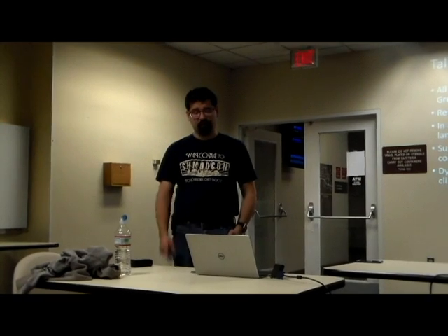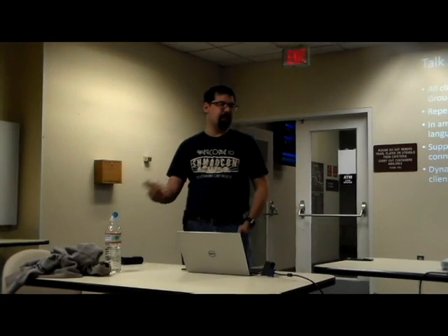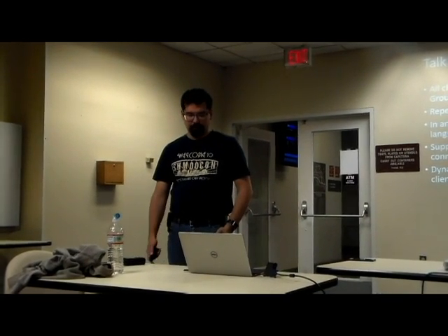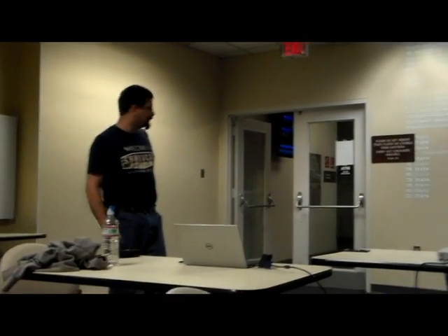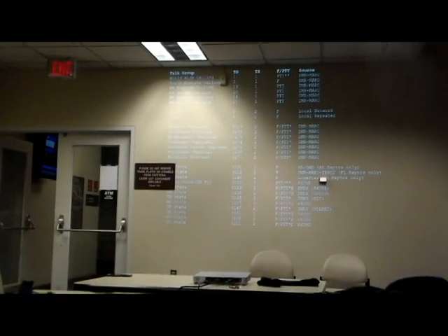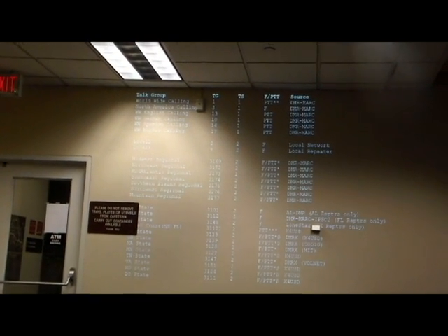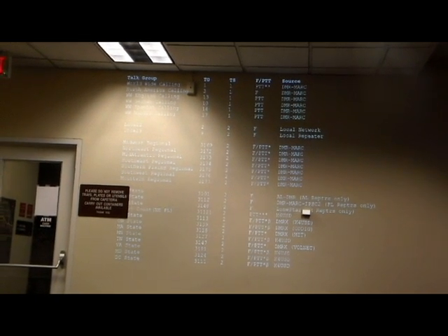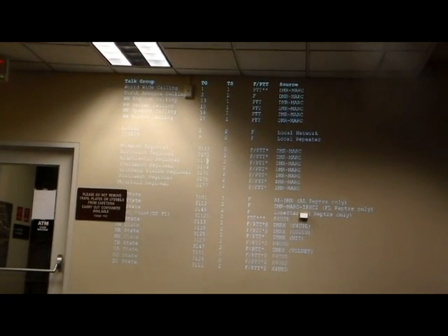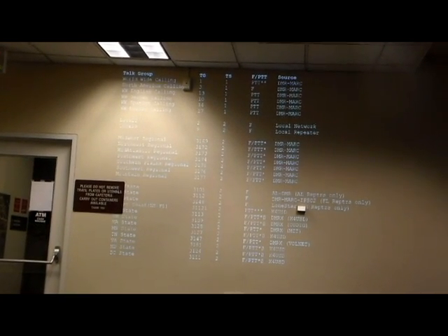Generally, when you do activate one of those dynamic groups, there's some kind of timeout involved with it, maybe 5 minutes, 10 minutes, something like that. And there are some consequences to that, which I'll get into a little bit. I'm not sure if this is readable, or at least somewhat readable. This is the list of talk groups that's offered by the K4USD repeater, or really the network that it's a part of. And you can see here, generally, again, most of them are regional or by state, something like that. These are the talk group IDs, and these are the time slots that they're offered on specifically on this repeater.